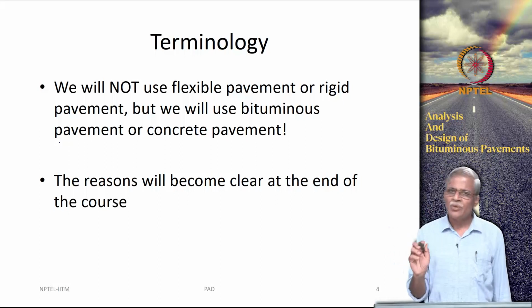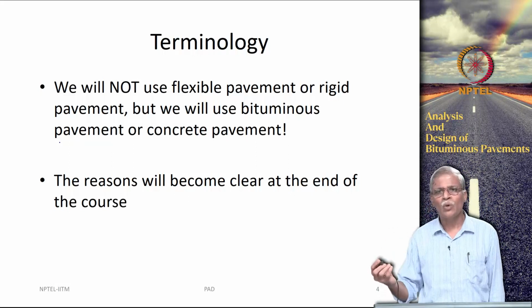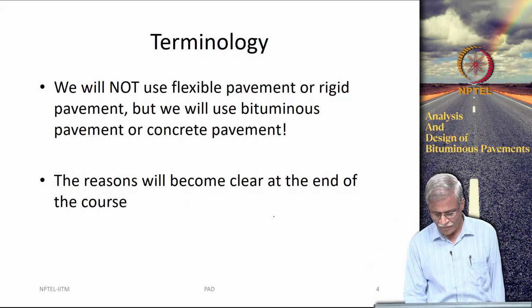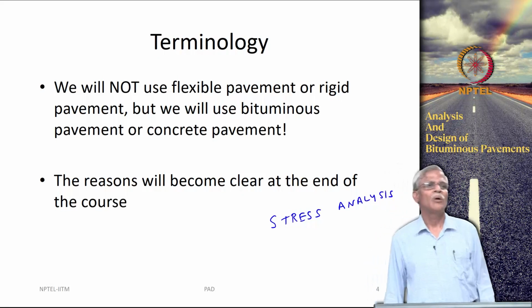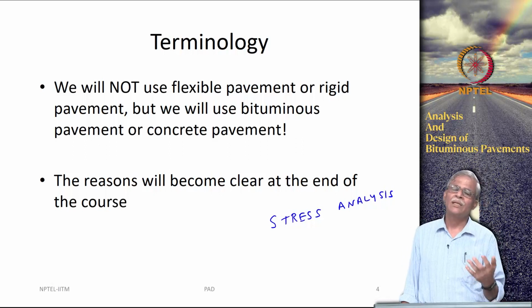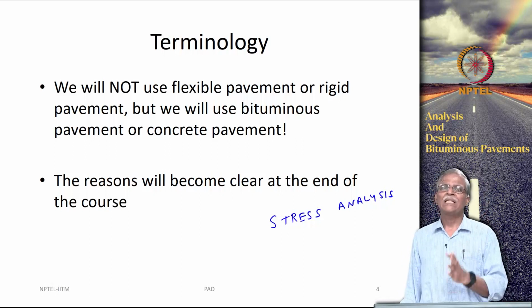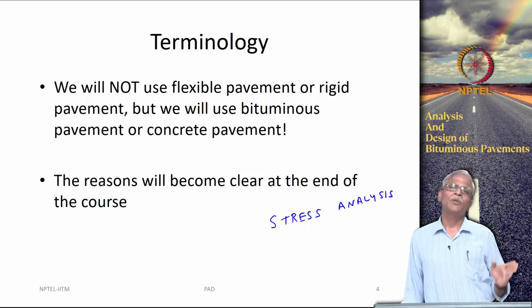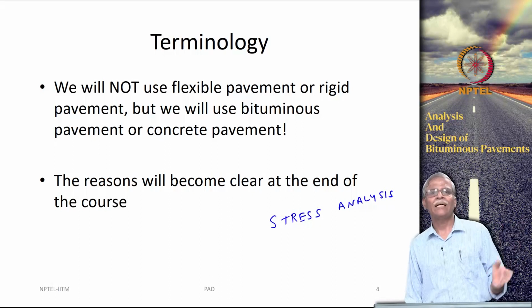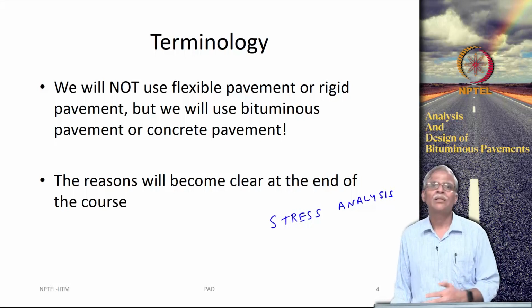Now, the reasons will become obvious to you as we go along, but I just want to give a hint. The reason why one should stick to bituminous pavement or concrete pavement is basically related to the stress analysis procedure that is followed. For bituminous pavement, we use what is called layered linear elastic theories.